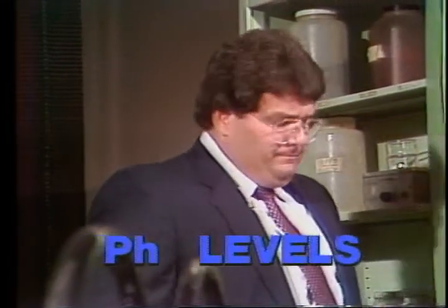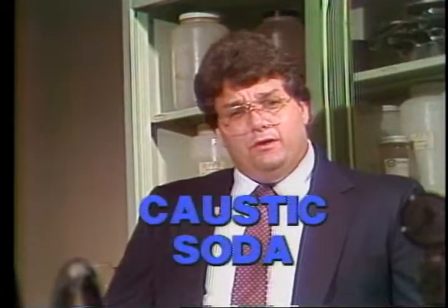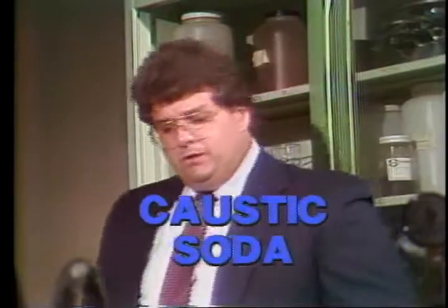pH is another concern. Dealing with pH control in mud systems requires the use of caustic soda, a very dangerous chemical to handle. So normally when pH is needed in various mud systems and caustic is added, it is normally added through a chemical barrel very, very slowly into the system. The reason being is that not only will caustic hurt yourself, but it will also contaminate and flocculate a mud system if added too fast. So care in both handling caustic and care in placing in the mud system is of utmost importance.